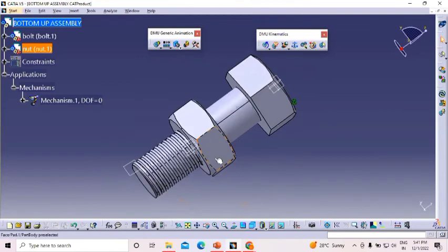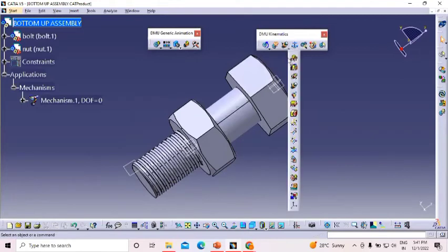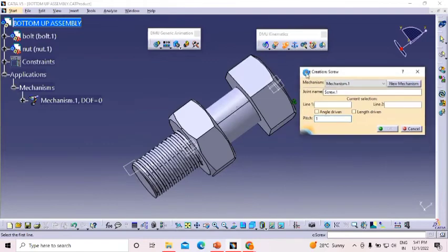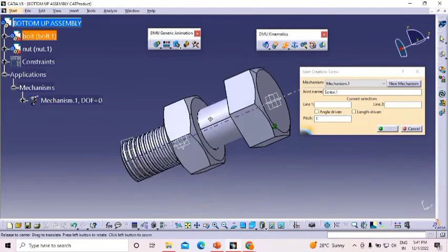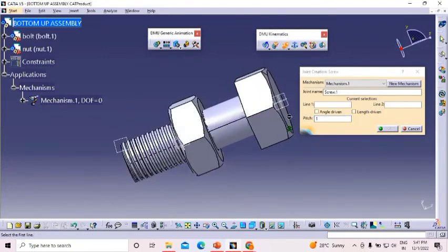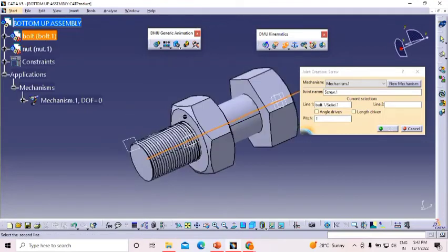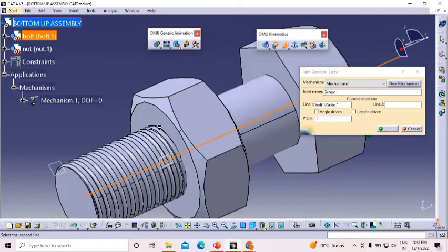Okay, so we have to give some joints, and if you expand here, lots of joints are available. For this one, a screw joint is required. So we have to provide the screw joint first, then we get the other product. We can give the simulation, and in the same way we have to give the line one, give some coaxiality, same process. Go for here. Okay, now it has been taken, and we also have to take care, but still we can't get access to the nut.